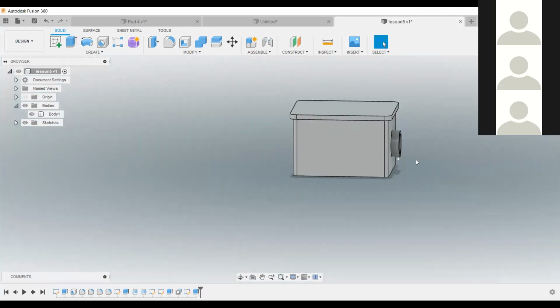So, you are still stuck. We are making a lid, okay, on top of our surface, or on top of our box. So how we are going to do it is by doing something called offset. So you offset that surface and then you extrude. So the lid is like 1 millimeter bigger than the actual box. So 1 or 2. So I want you to do this. And if you are stuck, call me, I will show you.